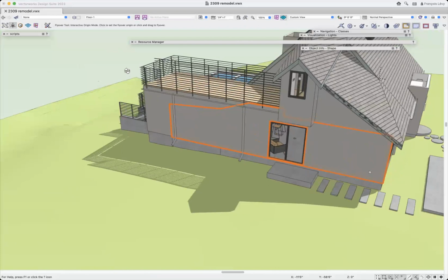So within a specific wall, because as Keith said, you don't have phases of walls. I couldn't phase out the old siding and phase in new stucco within the wall. Either the whole wall stays or the whole wall goes, is what I'm saying. Now, I could certainly assign a demo class to a certain component of that wall. I could put siding and then assign that siding to some sort of demolition class, but I couldn't occupy the same space with new stucco because wall components can't overlap.